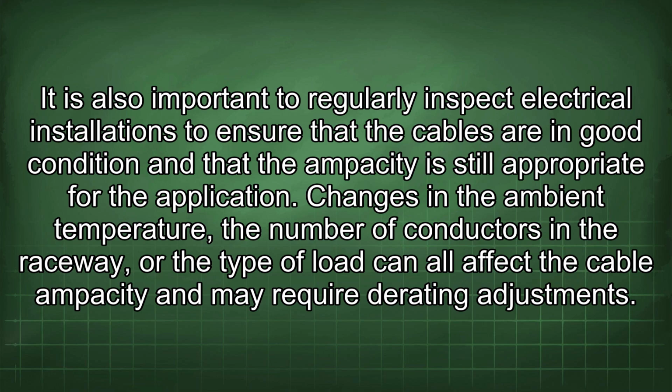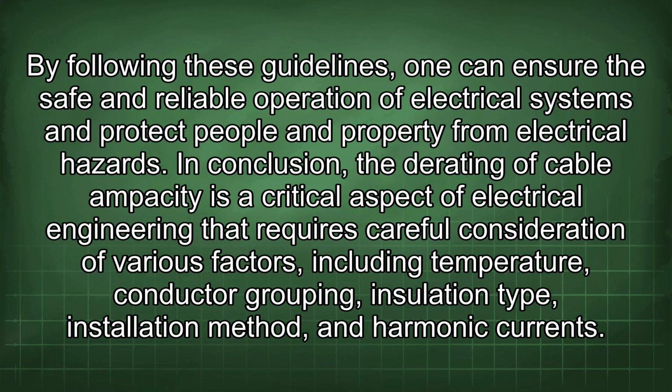Changes in the ambient temperature, the number of conductors in the raceway, or the type of load can all affect the cable ampacity and may require derating adjustments. By following these guidelines, one can ensure the safe and reliable operation of electrical systems and protect people and property from electrical hazards. In conclusion, the derating of cable ampacity is a critical aspect of electrical engineering that requires careful